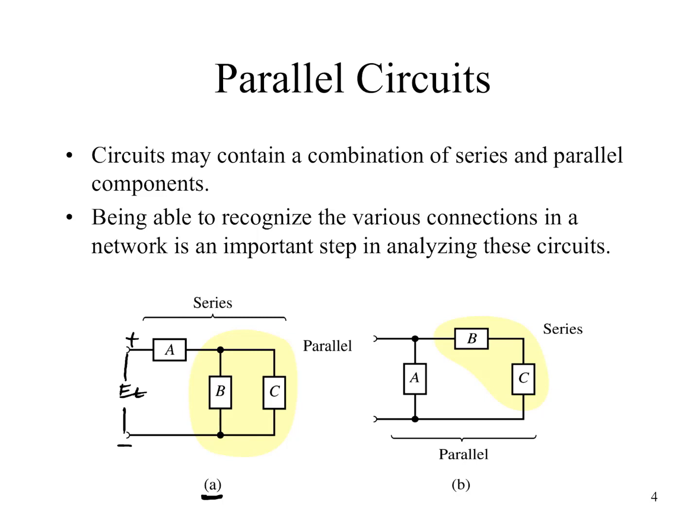So therefore, we could say that E total equals VA plus VB, or E total equals VA plus VC. And part of that is knowing that because parallel connections share the same voltage, VB equals VC.